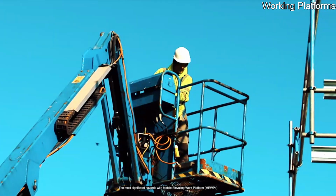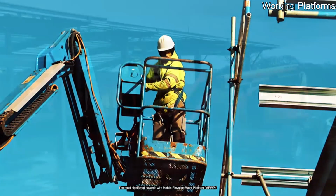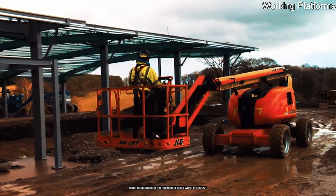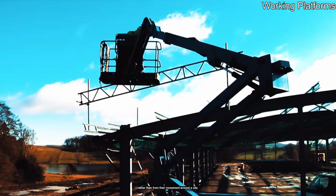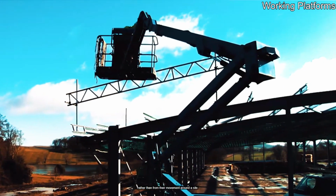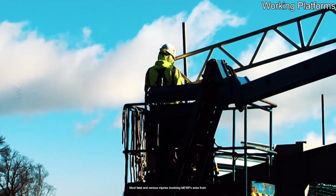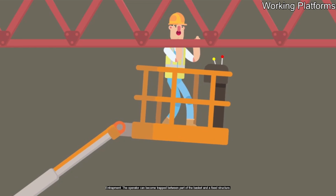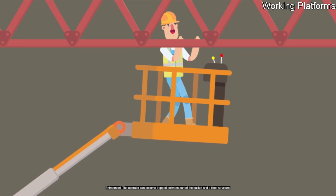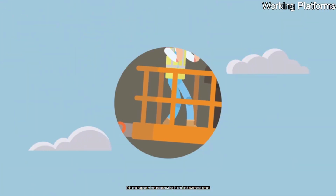The most significant hazards with mobile elevating work platforms, MEWPs, relate to operation of the machine or occur whilst it is in use, rather than from their movement around a site. Most fatal and serious injuries involving MEWPs arise from entrapment. The operator can become trapped between part of the basket and a fixed structure. This can happen when maneuvering in confined overhead areas.